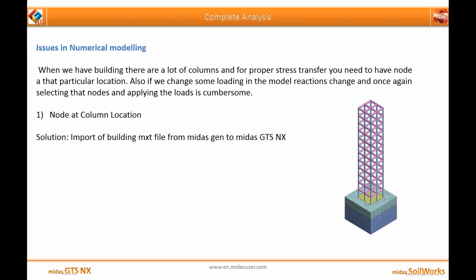For example, whenever you are creating a soil model and you want to apply a column load at a particular location, you should have a node at that particular location. And the second thing is you should know that coordinate also, or the node number also.